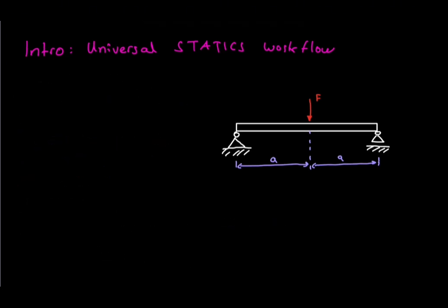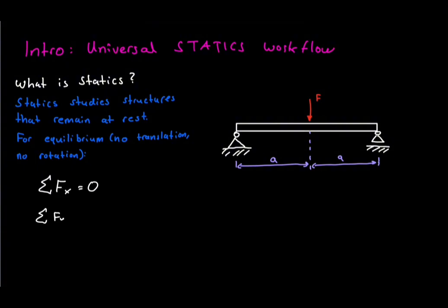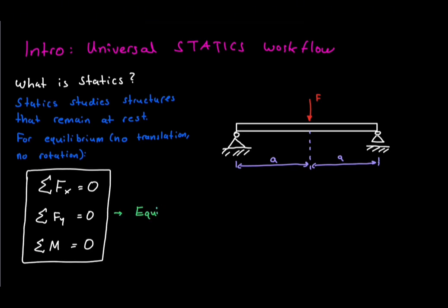Now let's talk about statics. Statics studies structures that remain at rest. If a structure is not moving and not rotating, it is in equilibrium. For equilibrium, three conditions must be satisfied. The sum of all horizontal forces must be zero. The sum of all vertical forces must be zero. And the sum of all moments must be zero. These are the most important equations in statics.